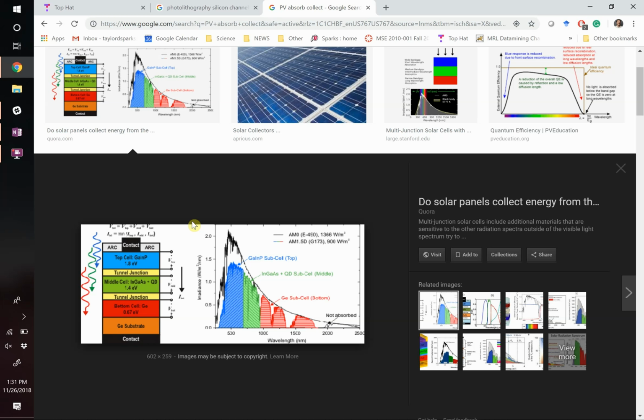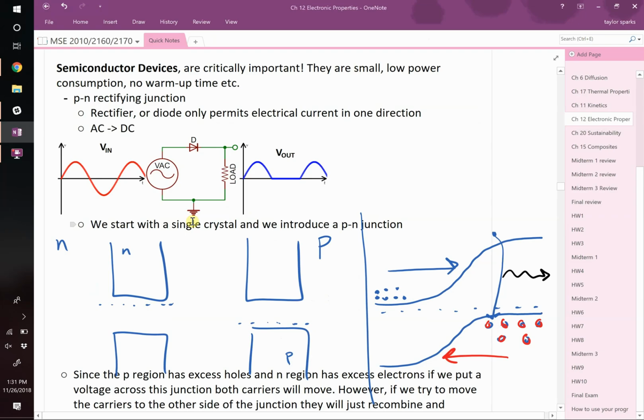So there's all these things you have to balance, but at the heart of solar cells is just a p-n junction. All you've done is you've created one of these, right? And light comes in, it goes up, and then you actually want it to get absorbed in this middle region, and then it gets depleted. Because you don't want recombination to occur. You don't want a solar cell to absorb light and then just become an LED and give that light right back off by these things falling back down and recombining. So you want this what's called a depletion region to exist.